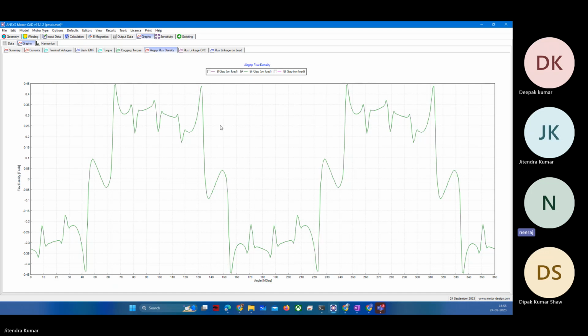Please elaborate this point, sir. See, this magnetic flux density will be generated near the air gap, right? And the air gap will see this kind of flux density, and this flux density will have a certain frequency. That frequency is nothing but how much? It is dependent on the speed and the number of poles. But that rotation and variation is happening inside the machine, not at the terminal. At the terminal, what you are providing to this motor is this current.